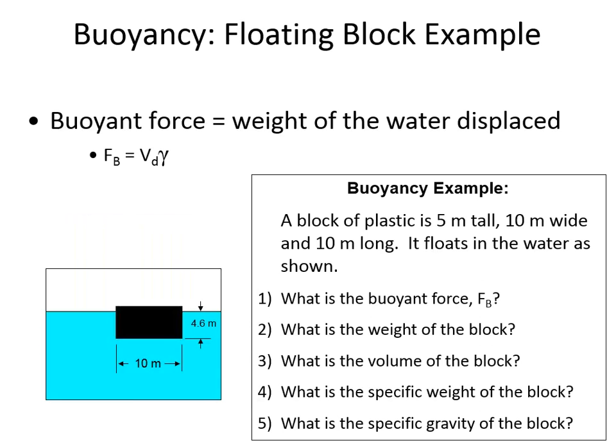Would this percentage work if you were using a liquid with water, like floating plastic in it? Yeah, well, then we'd need to make note of the fact that we'd have 2 different specific gravities. There would be the block versus water, and then there would be whatever liquid you're using versus water. So you'd have to do 2 conversions, but you could do the same kind of calculation.